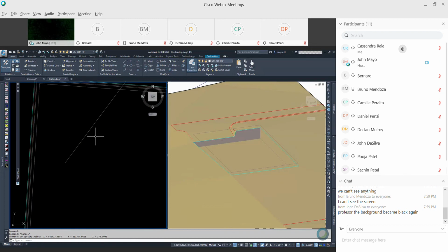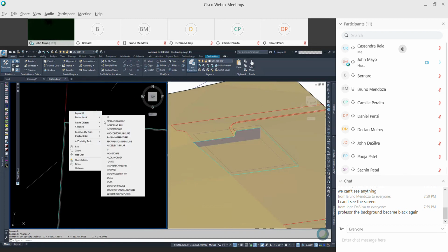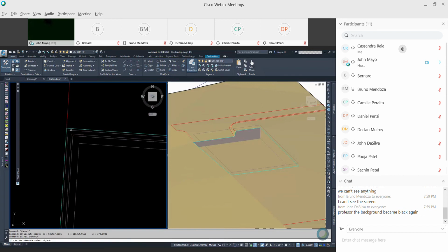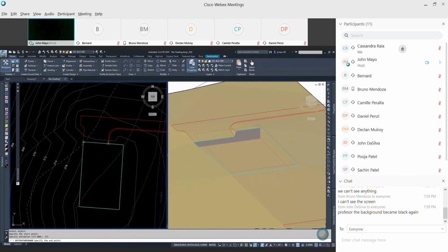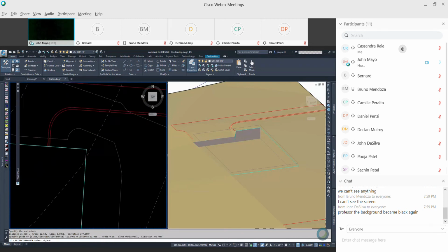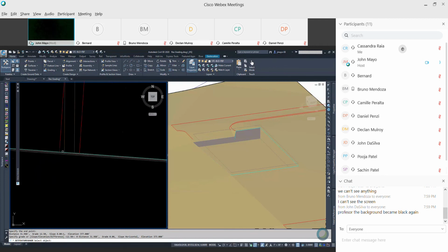So I'm at 373. Let's try putting that driveway at elevation 373. Come across my driveway at a grade of 0. And lift my wall 4 feet. And I hope you're paying attention to the command line. That's where I'm changing between grade and elevation difference. Right now I've got to get to a difference of 4.